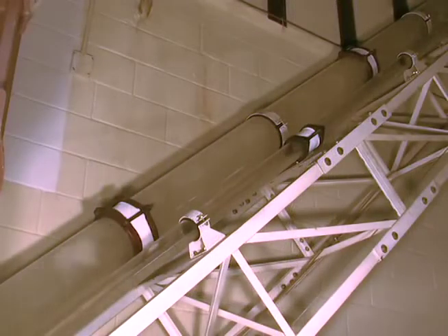The gas rate has now been increased slightly so that the bubble flow in the large tube has transitioned to more of a churn pattern. In the small tube, you see that now there are some long waves of the foam moving down.